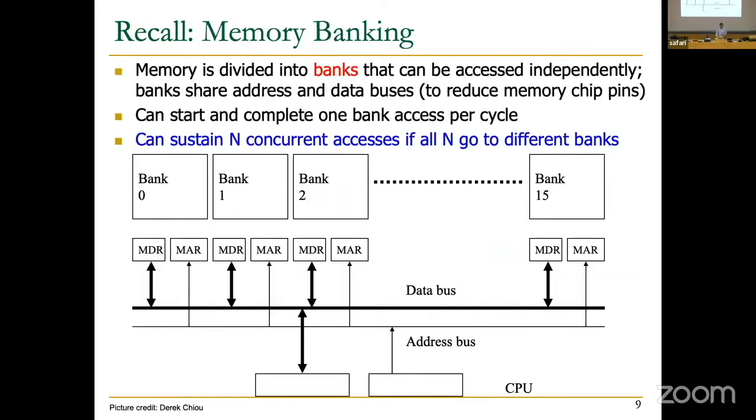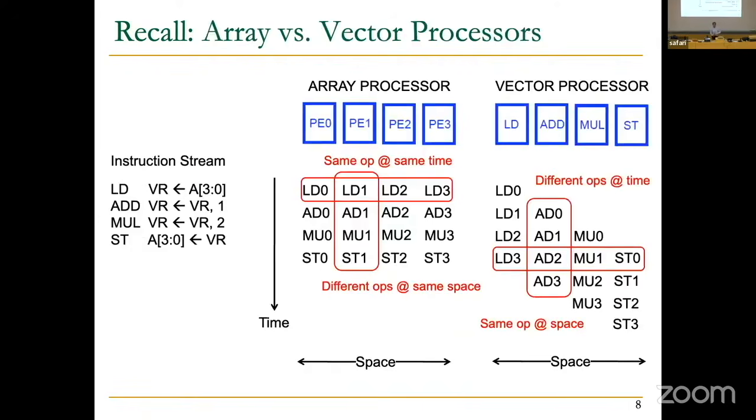And in real processors, we combine both of them. And we said that SIMD is very powerful because it enables a single instruction to specify huge amounts of work, because you're doing the same operation that's specified by the instruction on many, many elements, billions of elements potentially, right?